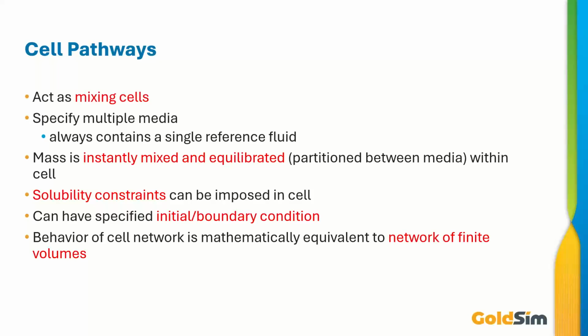In a real model, you often have to discretize your model because it's not appropriate to say that this part of the system is completely well mixed. In our case, our mixing cell is going to represent a tank or an entire plant that we've approximated as a tank. And we are going to assume it's all well mixed. It goes in, everything is mixed together. Maybe not instantaneously, but on the time frame of the time step we're dealing with, it's instantaneous.